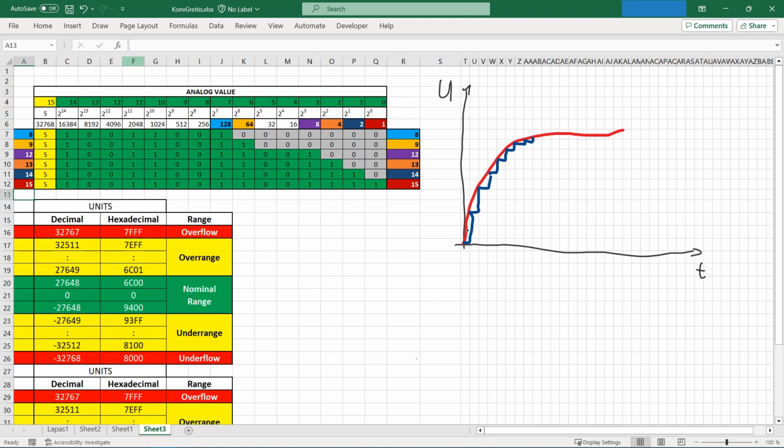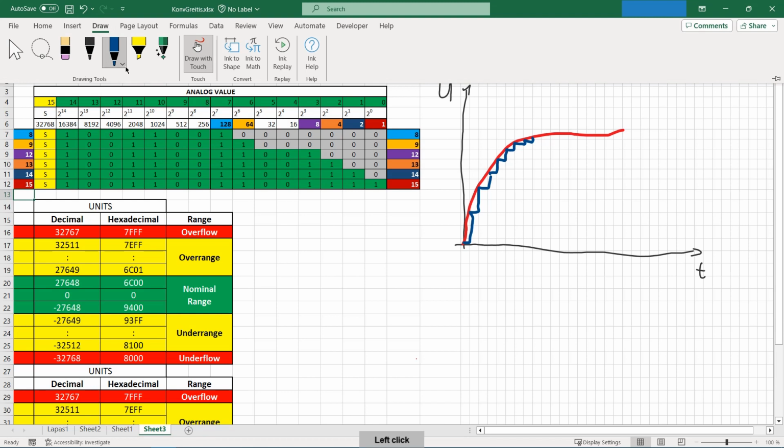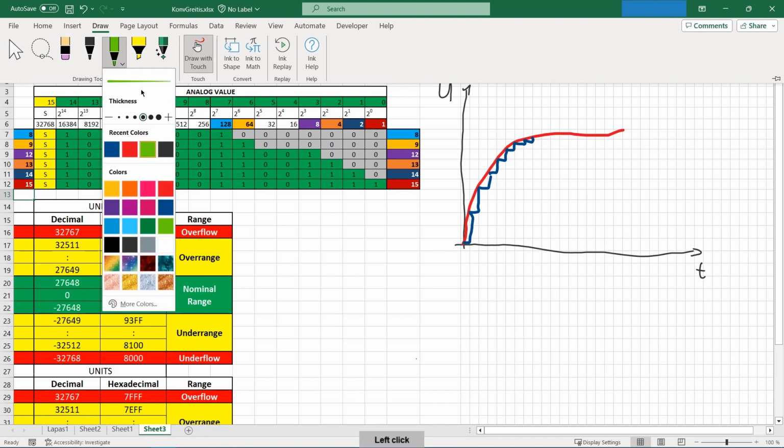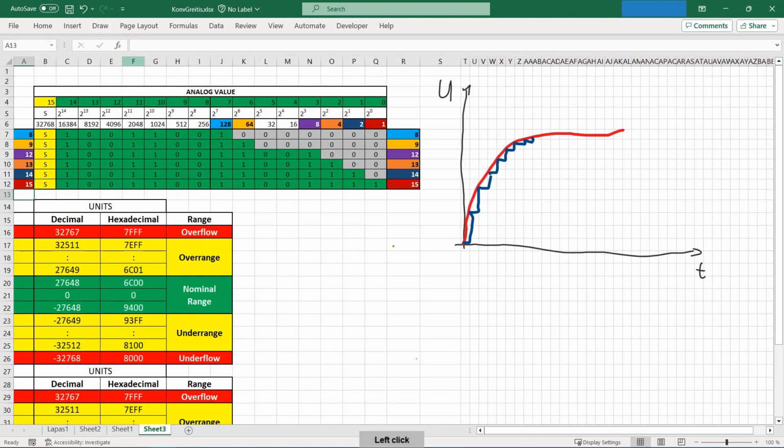Two most important parameters of the approximation are conversion speed and the resolution. In other words, resolution is precision. It depends on the converter and its circuits. As you can see, an approximation of the analog signal is returned as a step curve. The number of increments is directly proportional to the resolution. The shorter the length of the increments, the higher the resolution, and it adds precision.